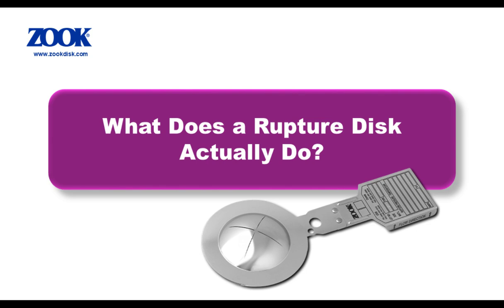What does a rupture disk actually do? A rupture disk is a differential pressure device. A proper rupture disk assembly creates an impermeable barrier in a pressurized system, and it bursts or opens when the differential in pressure across it reaches a designated level. We have a quick video to show you demonstrating a rupture disk opening. Let's play the video now.